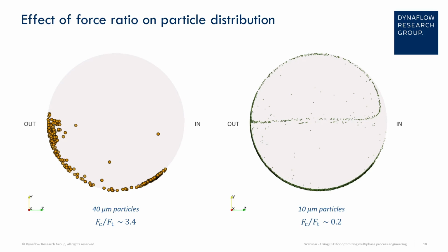But the important takeaway from this is that the chances of, for given flow conditions, having these particles uniformly distributed throughout the cross-section is highly unlikely for 40 micron particles, whereas for 10 micron particles, if you also take into account particle-to-particle interactions and change turbulence along the outer wall, you could sense that that would already be more probable. That is already very important for our client. So the bulk behavior of the flow, you can already draw conclusions on that.